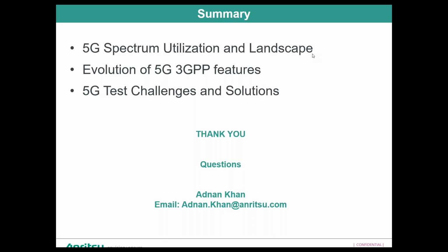So the chamber has to be characterized across different frequencies, and the 3GPP specification 38.810 defines exactly how. Basically we take an antenna at different angles of phi and theta. We take it at 7 different points, and we go around 5 different phi and 5 different thetas at different frequency ranges. The main thing is to characterize the quiet zone.